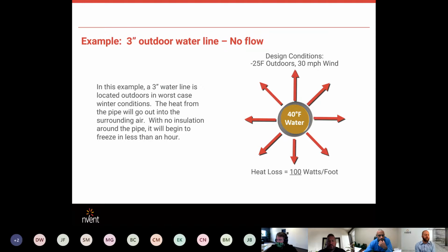So when we look at your heat tracing system and we're designing a system, and more importantly sizing the cable, choosing the correct cable for your application, what we're doing is looking at a single foot length of pipe section. Within that section is just a spool piece. We're not factoring in any valves, supports, and flanges in that particular portion. Looking at a straight length of pipe.